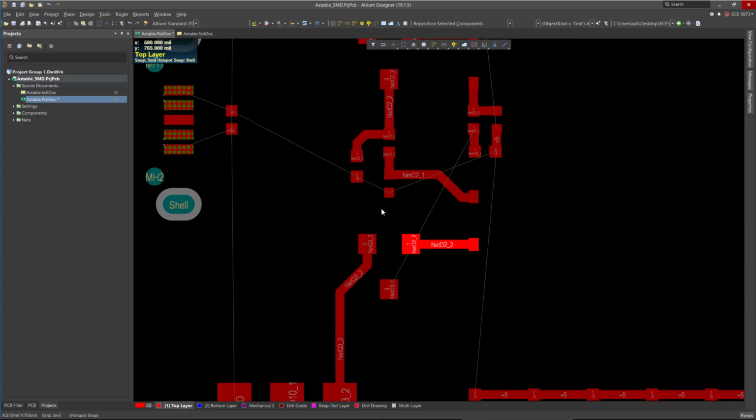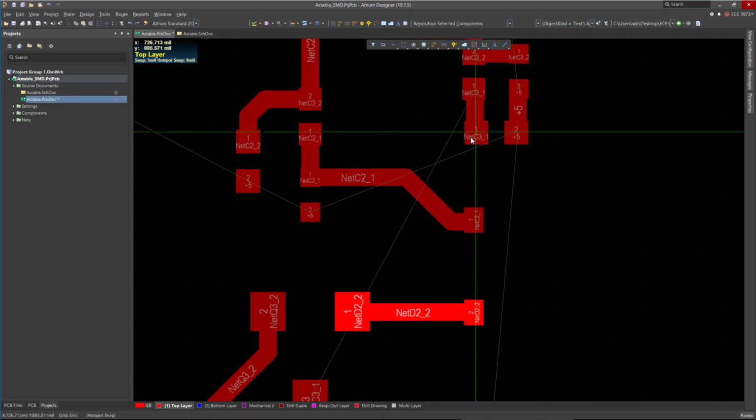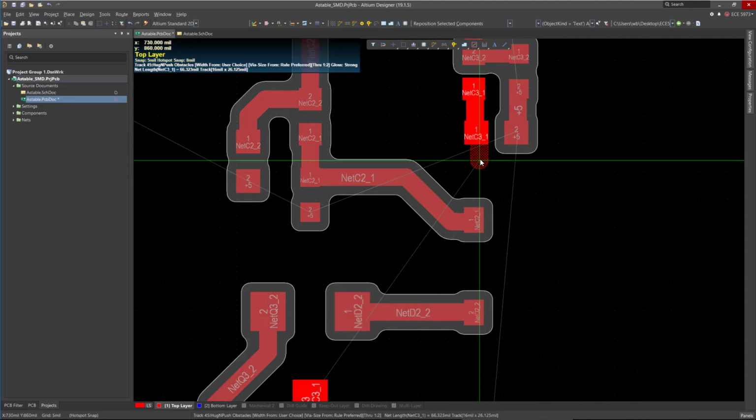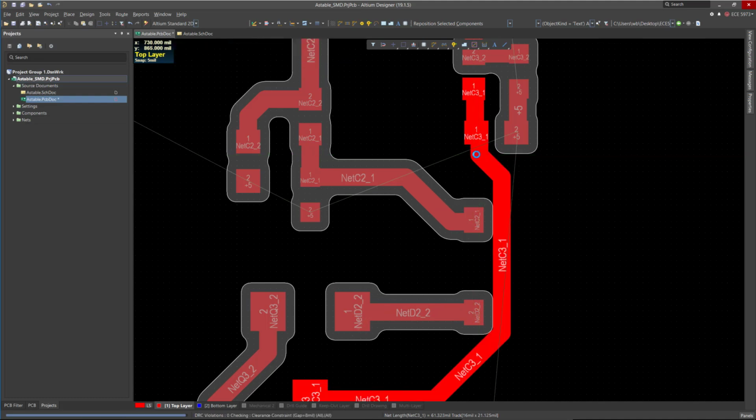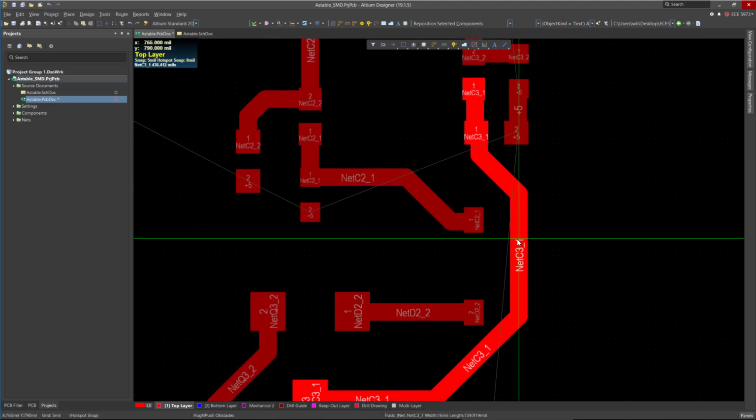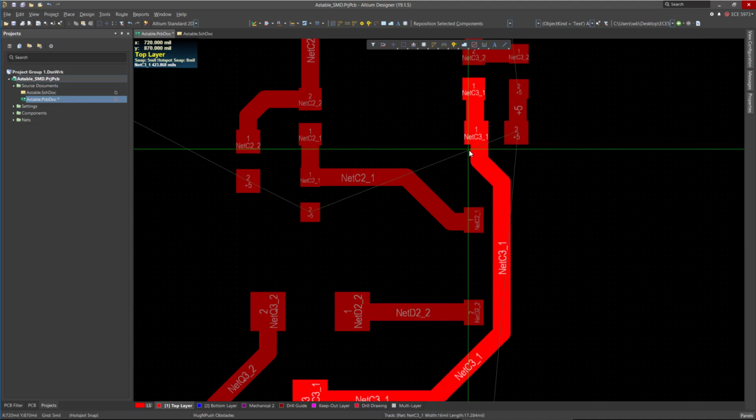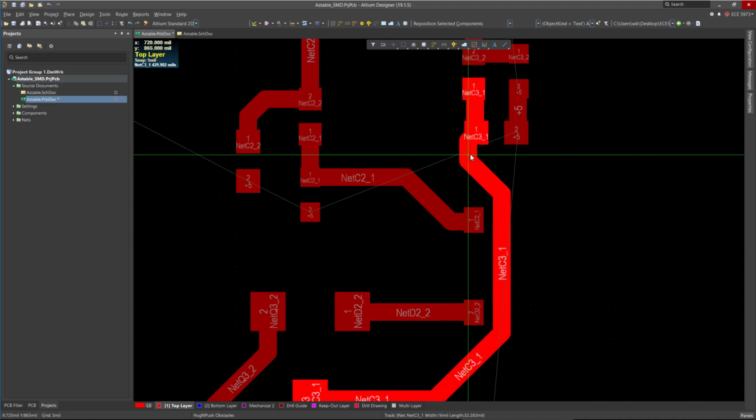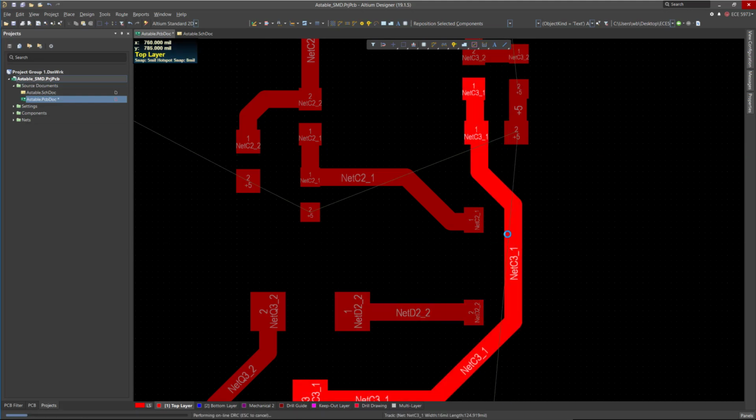So here we will see, we are going to use a VS for this 5 volt. We can route it from here. We have trace, but okay, let's see this. So if I hold control down and left click in the mouse, Altium Designer will do auto routing for this trace. Yes, you still need to adjust the traces, fine tune them.